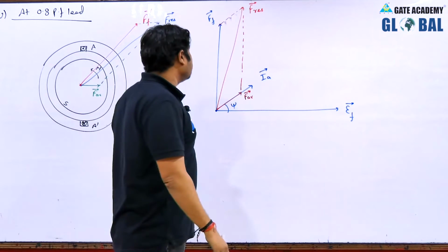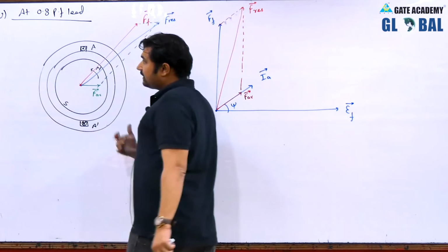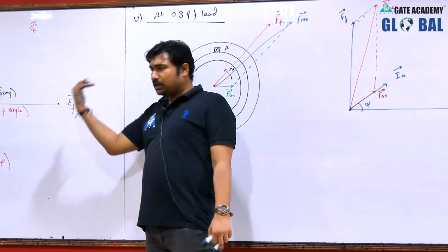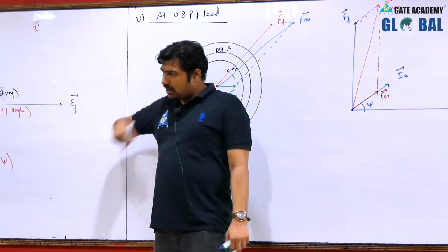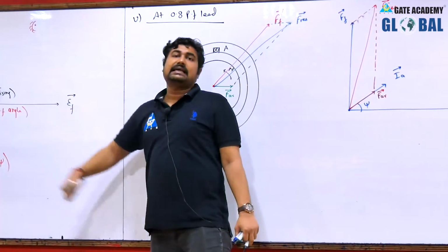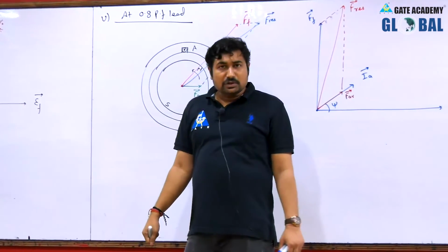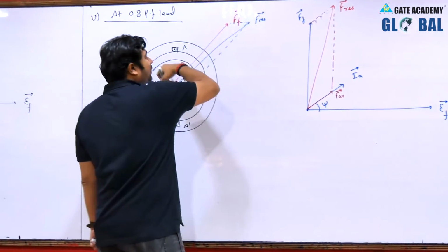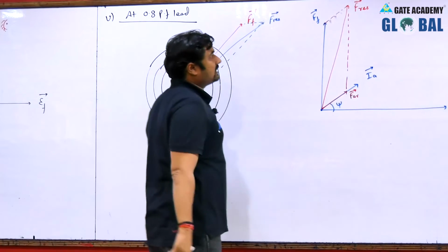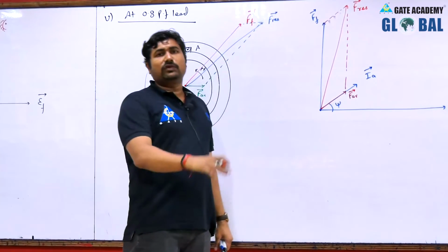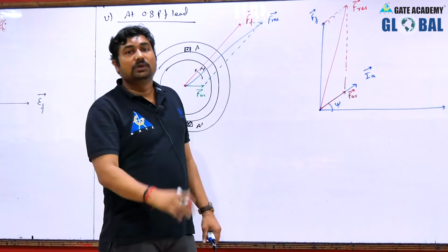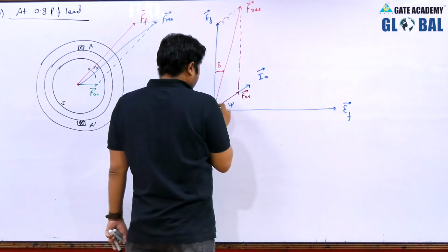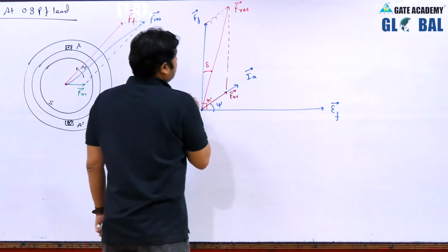That is the compulsory thing, because the generator can only generate when the rotor north tries to align towards the stator south, and you are providing motion against this electromagnetic torque. Is it okay? So, in case of generator, always the rotor field is ahead of the stator field, and that is why we always say that the power always flows from higher load angle to lower load angle. Is it okay? So, you can say this to be the load angle delta, this is your 90 degree.